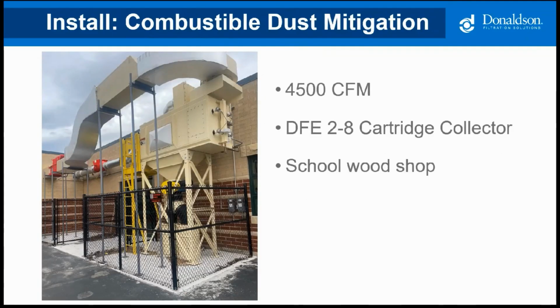This is a recent job we did at a school shop in Wisconsin. This is actually a small cartridge collector. Since the airflow was pretty low at 4,500 CFM, we didn't need a baghouse. We could go with the more economical, smaller size cartridge collector.